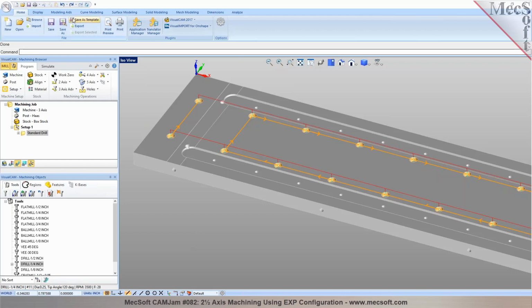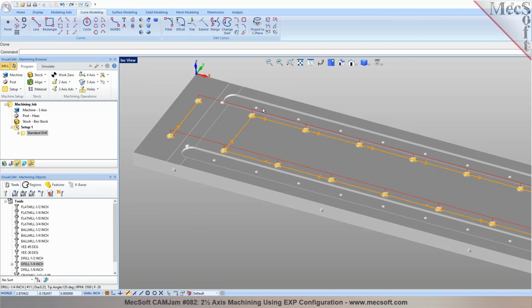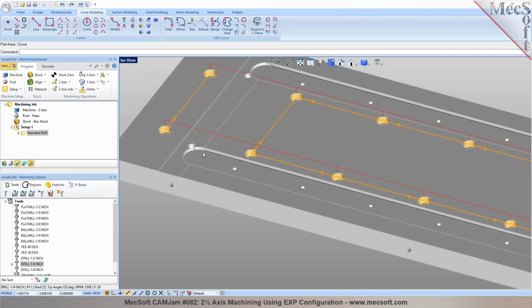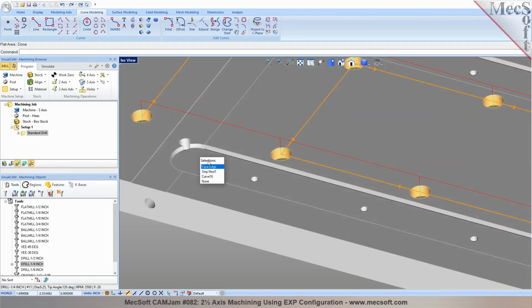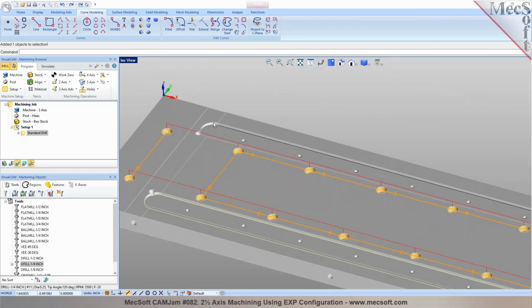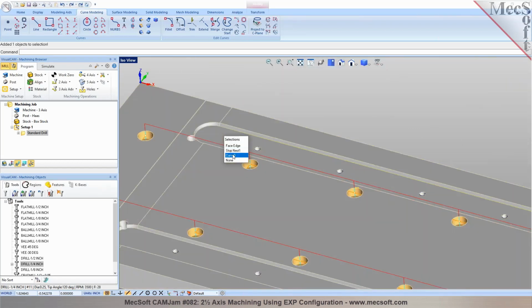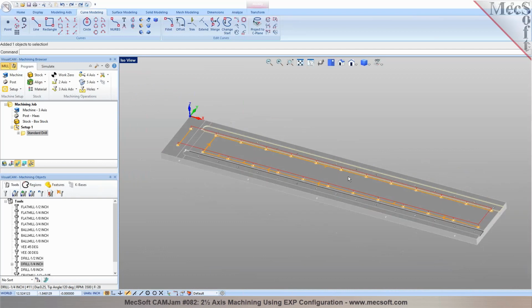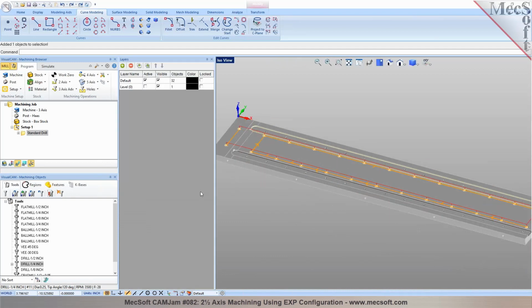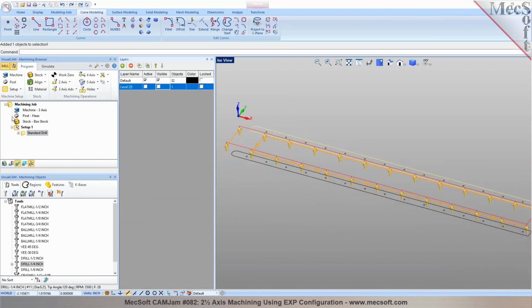One of the ways I could do it is extract what is called a sketch from this part. I can use this tool called flat area, and I can just pick this face, and repeat the same step to pick this face right in here, and this actually creates a boundary. As you can see, it creates this curve boundary around the part. It creates those curves, and I can also place them on a different layer, so that way you can see those curves that were extracted in here.